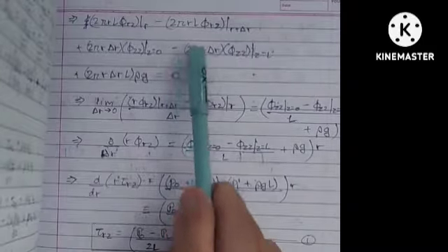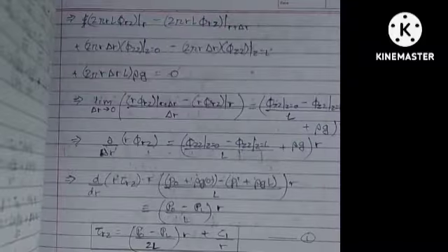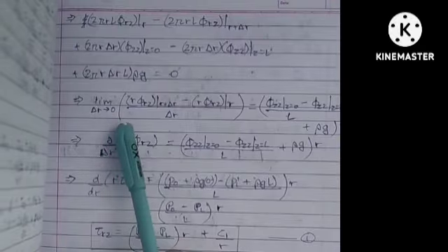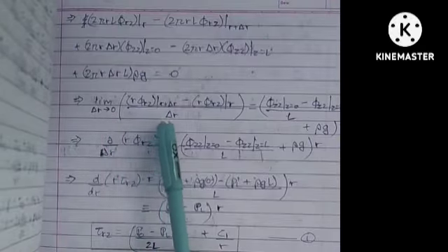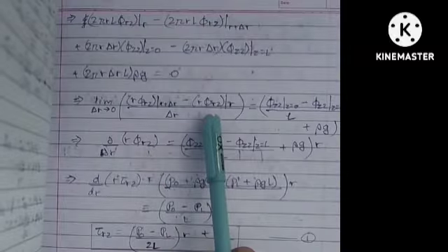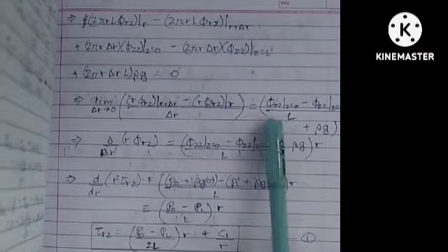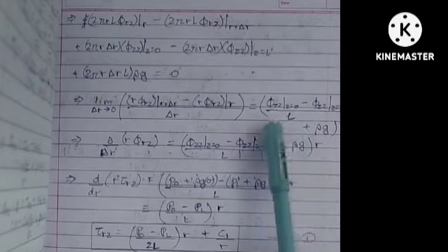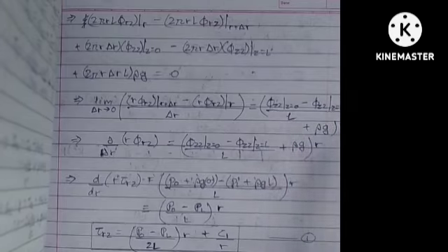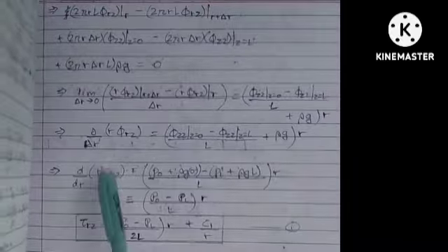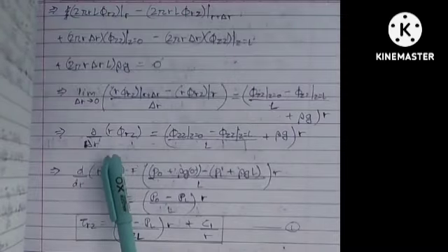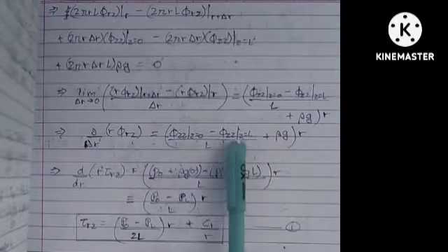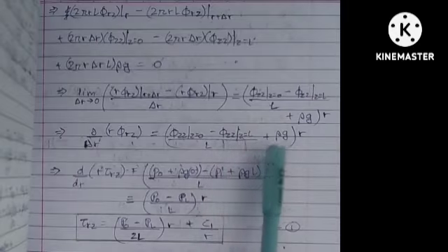Now, rearranging and applying limits, it gives limit Δr tending to 0, (r φrz at r plus Δr minus r φrz at r) upon Δr is equal to (φzz at z equal to 0 minus φzz at z equal to L) upon L plus ρg into r, which gives ∂/∂r of r φrz is equal to (φzz at z equal to 0 minus φzz at z equal to L) upon L plus ρg into r,